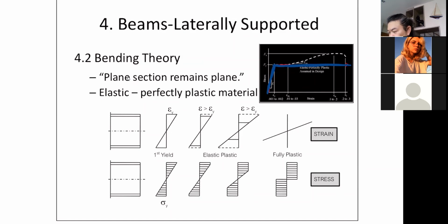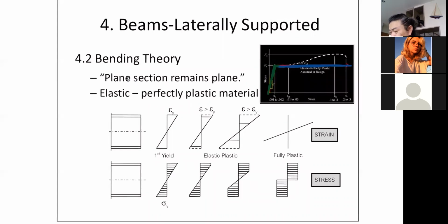This first part here is elastic, correct? I have to keep doing this so that you can see better. That's elastic. And this one goes flat. It means that when you reach this, your Fy will not increase, but your strain keeps on increasing. That is when you have the behavior called plastic. So you have the elastic here, and then you have the plastic there.